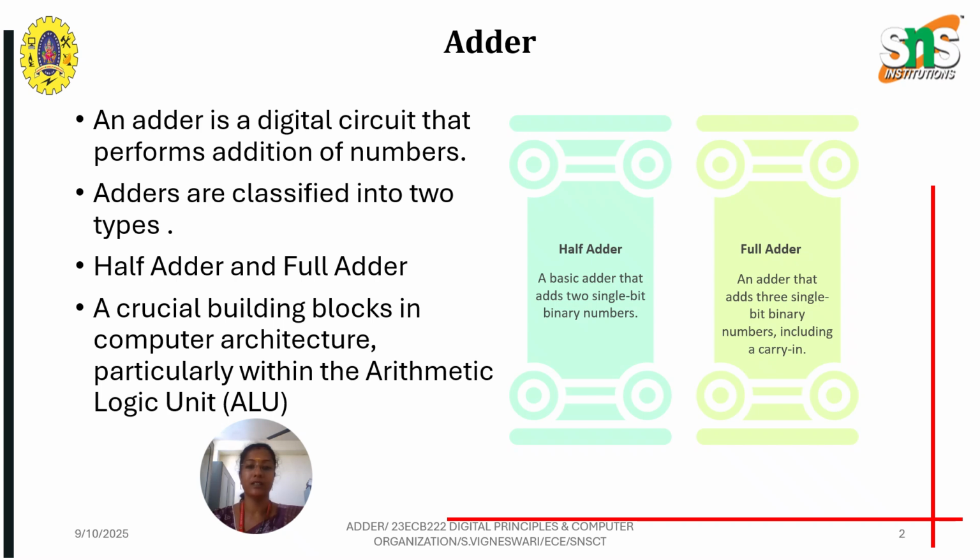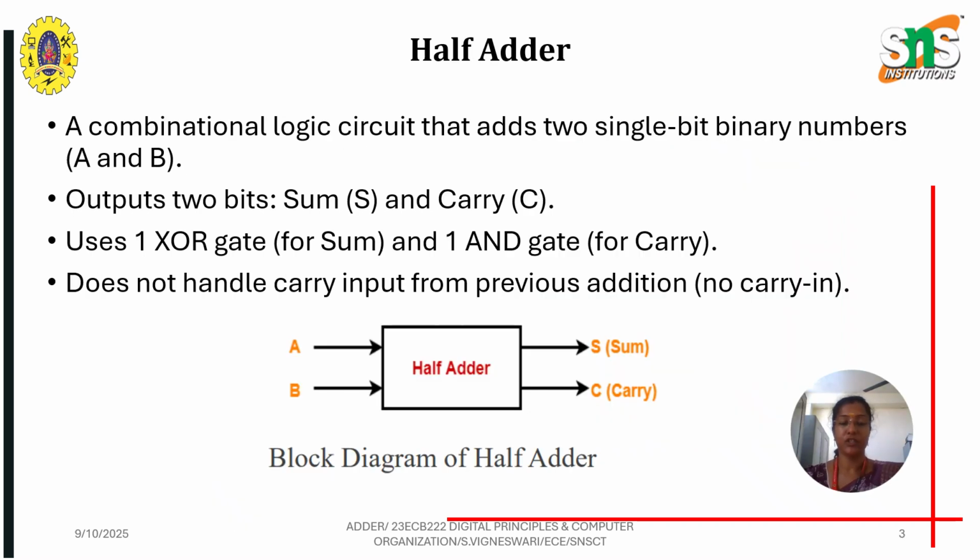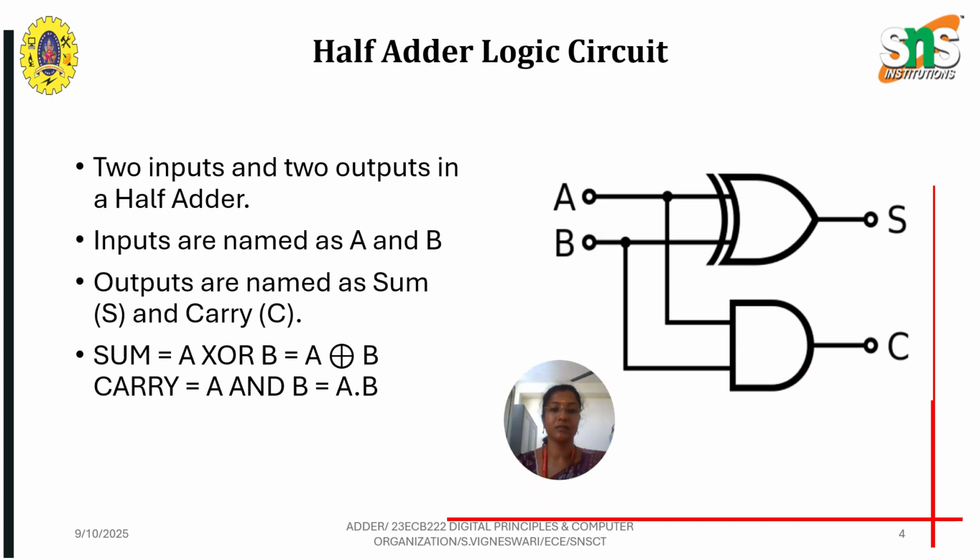So what is a half adder? Half adder is a combinational circuit that performs the addition of two single bit numbers, and provides the result of either sum and also carry. So here A and B act as the inputs to the half adder circuit, and S refers to the sum and C refers to the carry. So the sum and carry are the outputs of the half adder circuit. Half adders are used for simple calculations because this covers only two 1-bit additions.